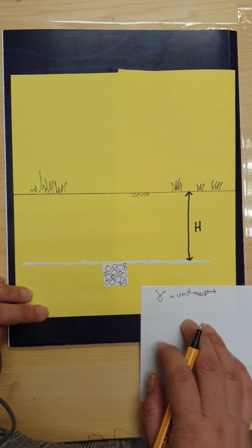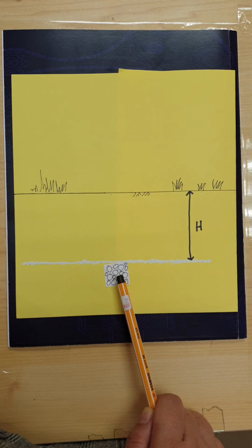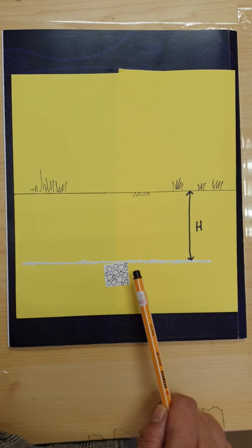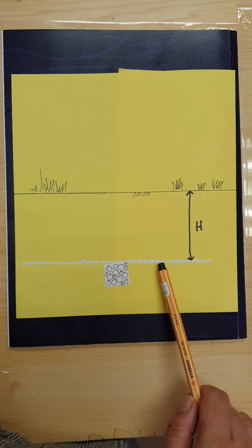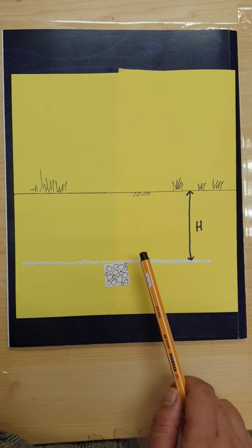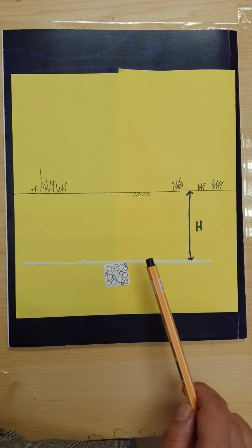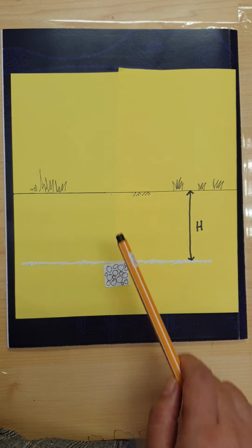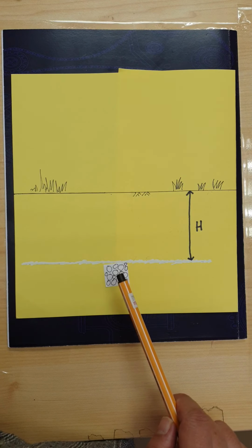In this case, we want to analyze under total stress analysis. Total stress analysis means that you have a point, and whatever is on top of that point, either inside the ground or outside the ground, you will consider all the load that acts on this point. So if you have water here, or you have a building around here, every stress will act on this point.